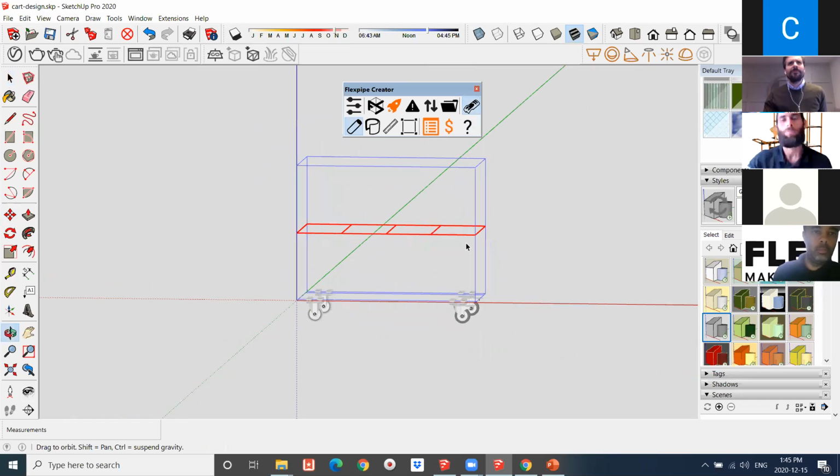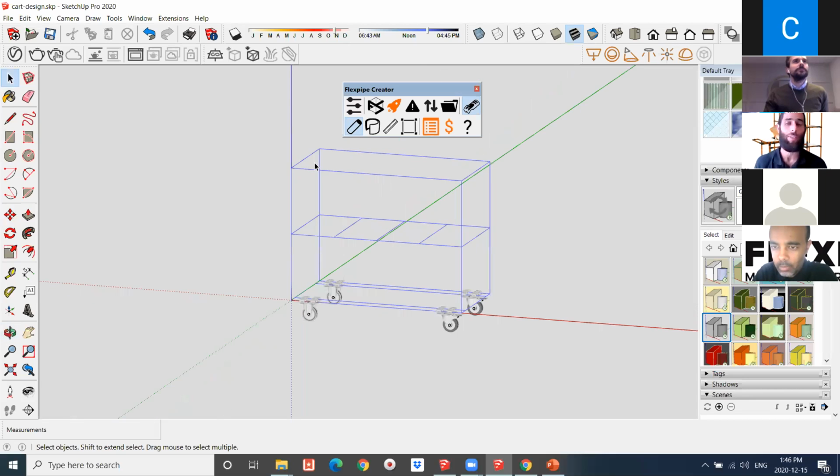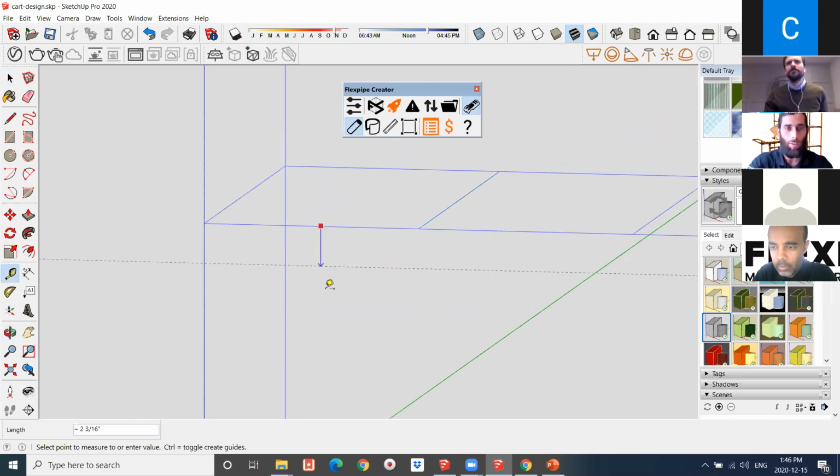Okay, good. So basically, we're talking about reinforcing this second shelving here. Okay, so we have two types of angles that we can use, right? We have a fixed 45-degree, and then we also have a multiple angle connector, which you can adjust to different angles depending on the setup of your structure. If you can get away with using fixed 45 degrees, I recommend those. They're going to be solid. They're not going anywhere, and a triangle is the strongest shape we know of.